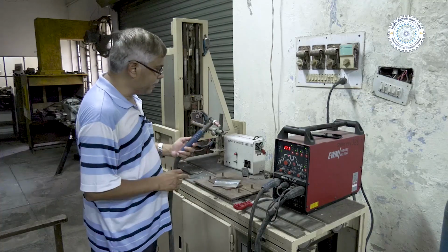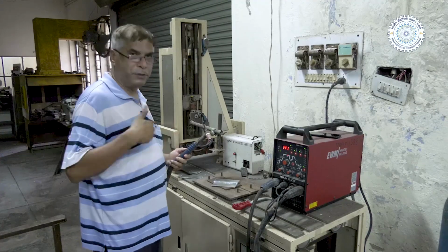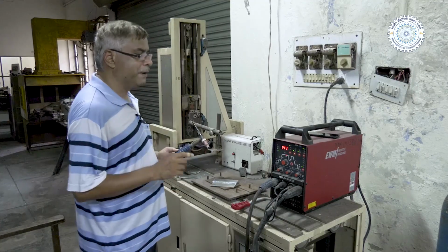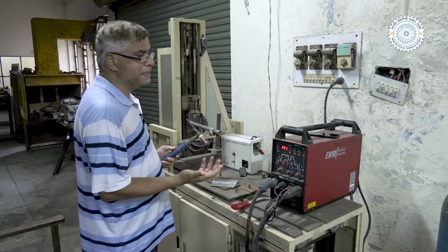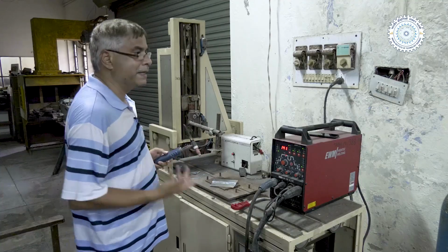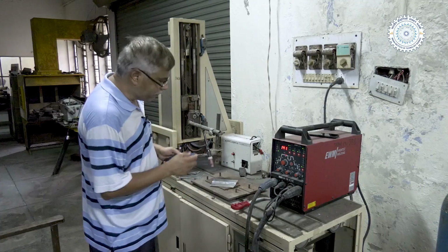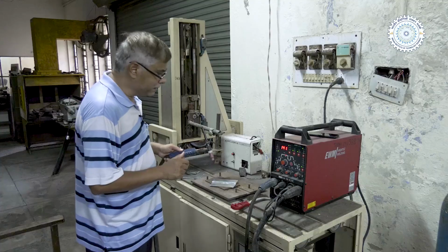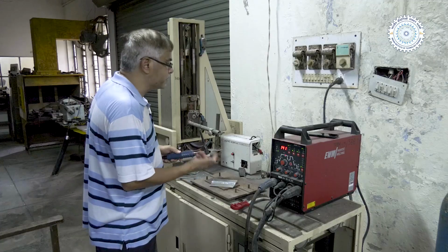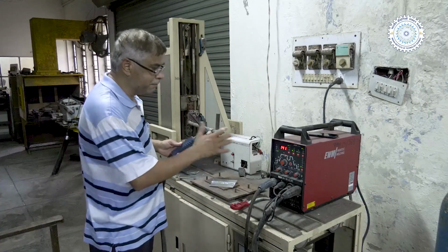Since this is a tungsten inert gas process, it uses the tungsten electrode, and for protecting the weld metal from the atmospheric gases, an inert gas is used as a shielding gas, which is supplied through a suitable cylinder of argon or helium as per the quality, purpose or criticality of the application for which the joint is to be developed. Since the process works at a very low level of current, heat generation is very less, and therefore thermal damage to the base metal because of the welding will also be limited. So now we have seen the different parts and components.